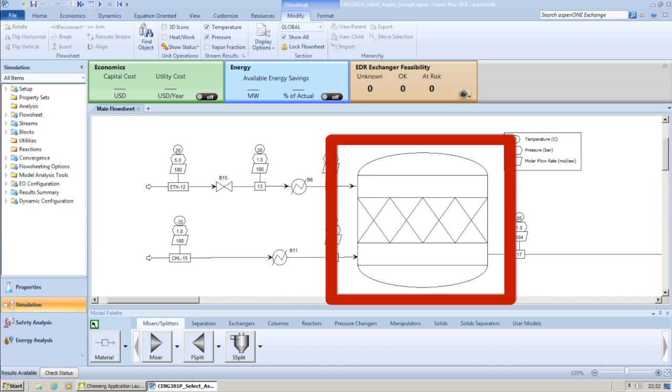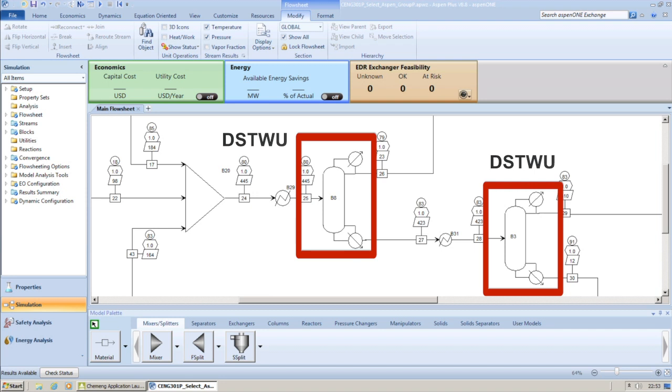In Aspen, you can choose to use various models to represent each reactor and distillation column. We chose to use RStoic for the reactors. This is to allow us to define multiple reactions with fractional conversions being stated. Also, the heat of reaction can be calculated from this model. Another consideration was RYield, however due to the lack of stoichiometric inputs, heat of reaction would not be calculated. The columns were modeled using DSTWU due to the fact that it is a reasonable initial estimate, and when compared to literature values the results were similar.